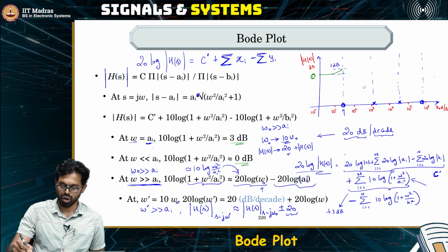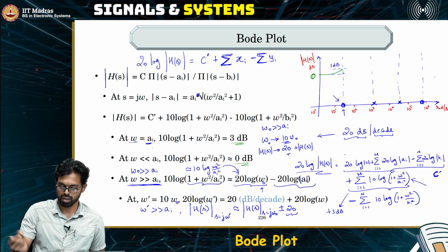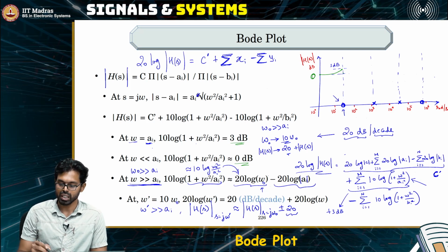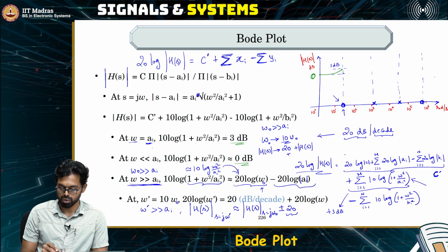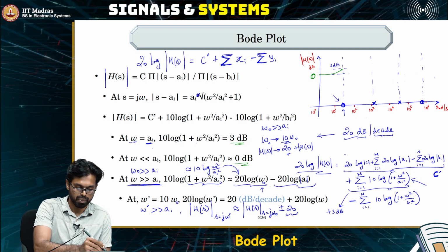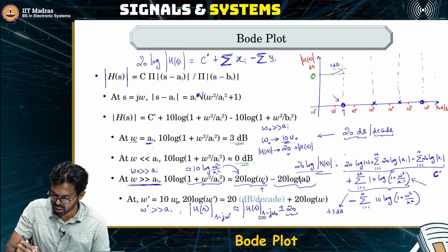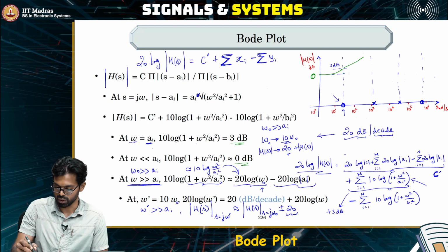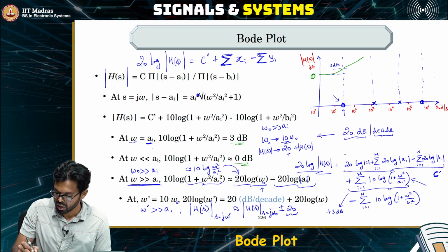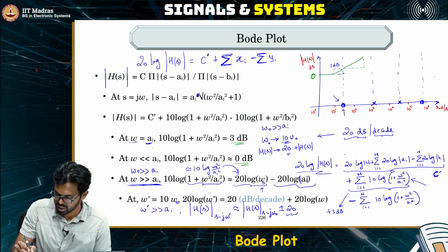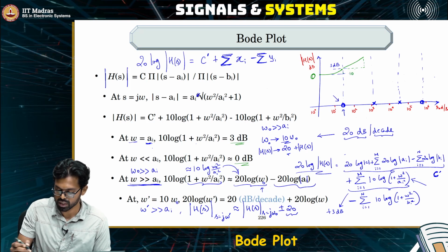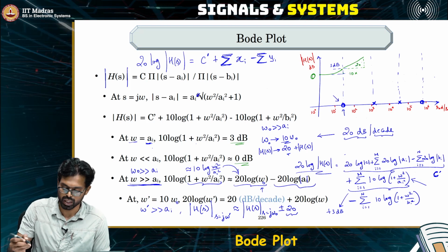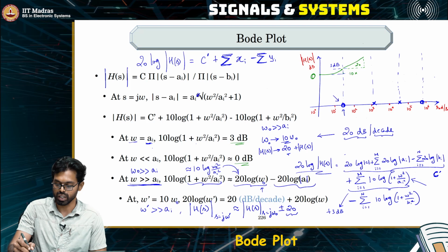Okay, so the effect of this particular 0 is now going to cause an increase of the transfer function's magnitude by 20 dB per decade, meaning what we have to do is we have to keep increasing this transfer function's magnitude such that, let us say, a 10 times increase in the frequency value, then this is 20 dB. So then the y-axis intercept should be 20 dB.